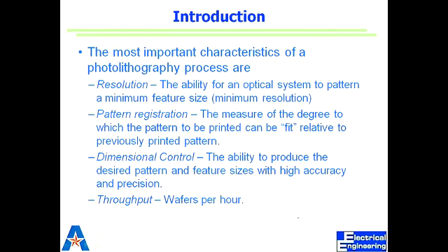Right. So, I'll tell you, a machine with 1 micron error in registration is fine if my feature size is 10 micron. It's just 10%. But if my feature size is 5 micron, my registration error is now 20%. So it keeps on going up. I have to inspect to see my registration is good.